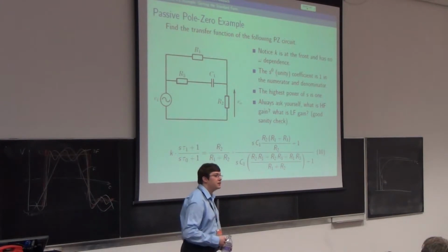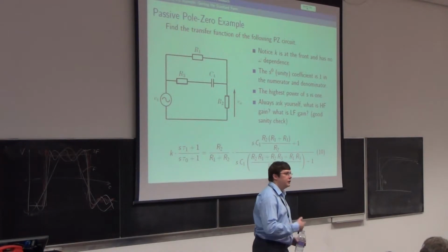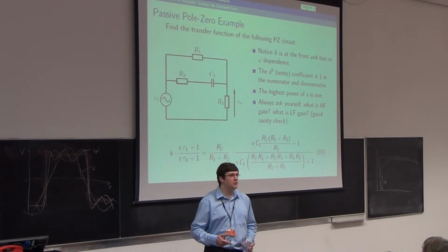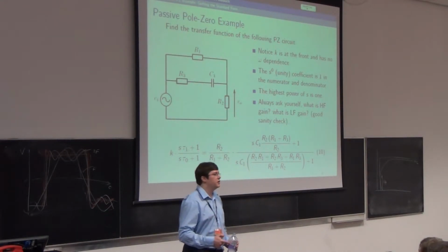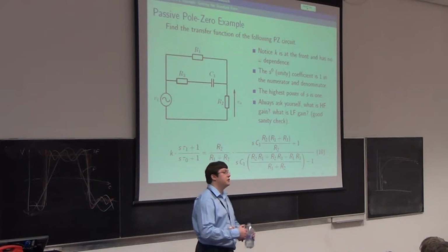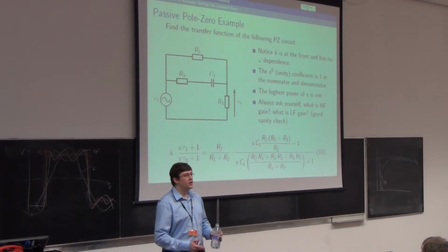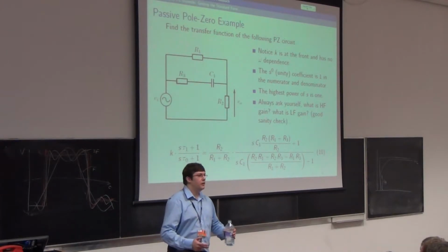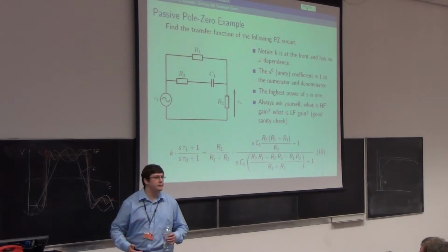So if you did have a second order system, you'd have s squared on the bottom, and you'd have s squared on the top if it was high pass, s on the top if it was band pass, and 1, that's to say s to the 0, on the top if it was low pass. You cannot have s to the 3 on the top with s to the 2 on the bottom. Well, you can do whatever you like mathematically, but there is no physical circuit that can realise that system. And there is no arrangement of springs and masses and oil-filled dampers that can do it either. You can't do it mechanically.